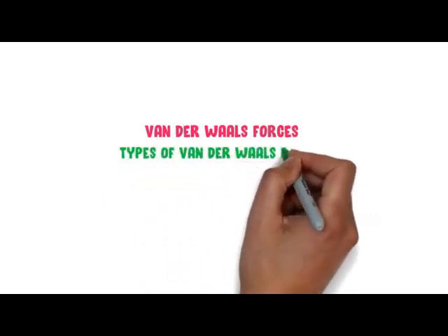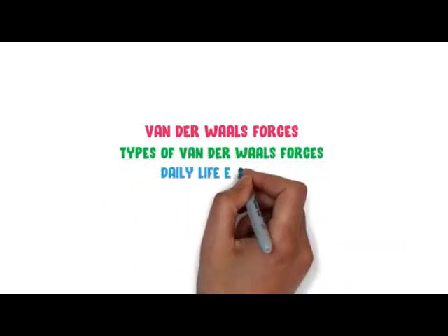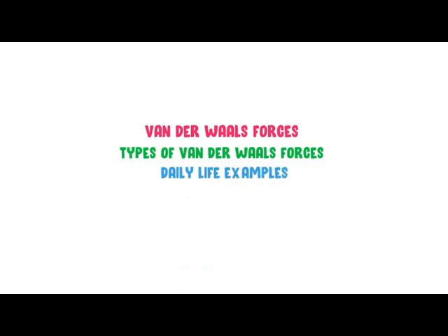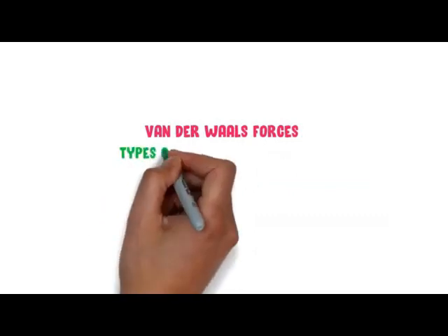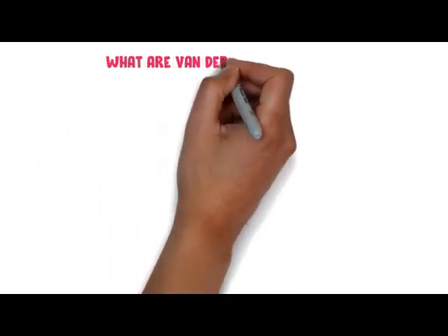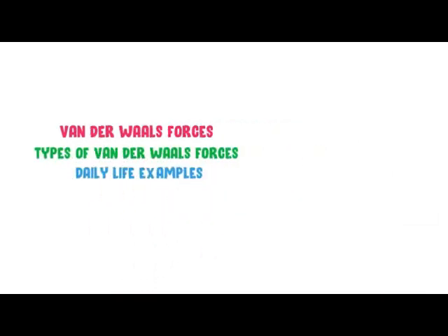Another bonding type is van der Waals force. They are very small forces of attraction acting between atoms in the case where the formation of an ionic or covalent bond is not possible. Basically, similar forces also act between atoms which are already bonded in neighboring molecules, giving rise to the weak van der Waals force between long chain molecules in polymers.